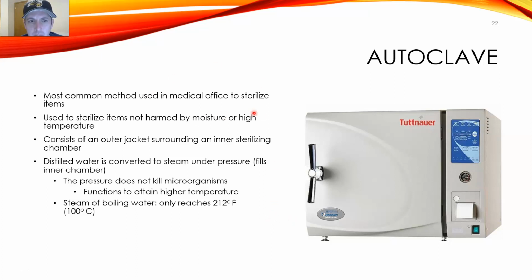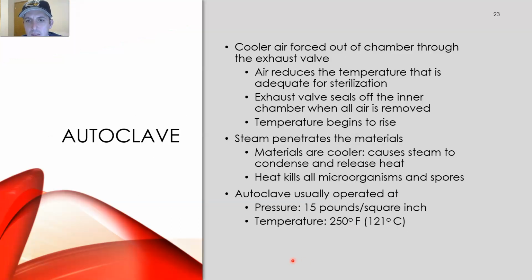The process with this is it's going to use high pressure and steam to get these instruments at a high enough temperature to kill all of those bacterial spores in particular. And so the pressure really just helps to attain that higher temperature, because that's what the real focus is, to get that temperature there.